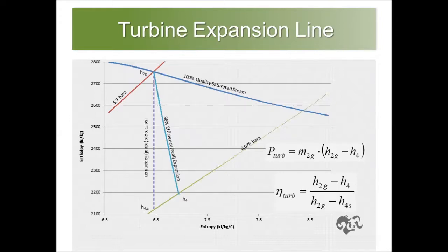Another difference is the fact that your actual turbine consists of a series of expansions across a number of stages. At each rotating stage discharge, the steam will gain a little entropy before expanding through the next rotating stage. So the path actually follows a zigzag pattern.